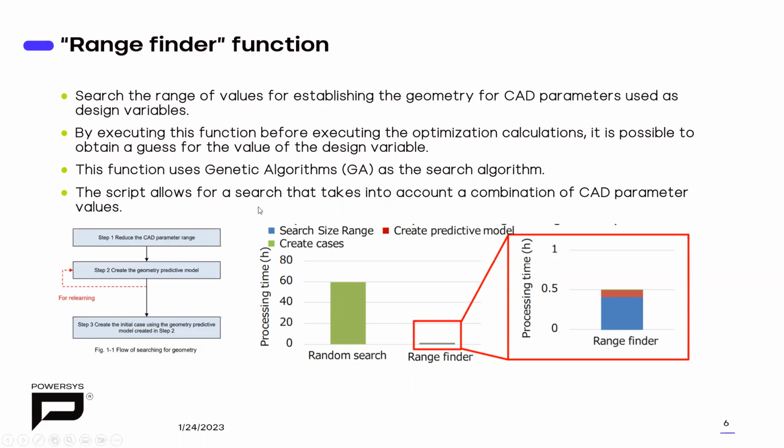JMAG will do that for you. In addition to that, JMAG will also create a predictive model, so that with a specific amount of geometry already tested, JMAG will be able to guess in advance if those new sets of parameters will give a valid geometry or not.